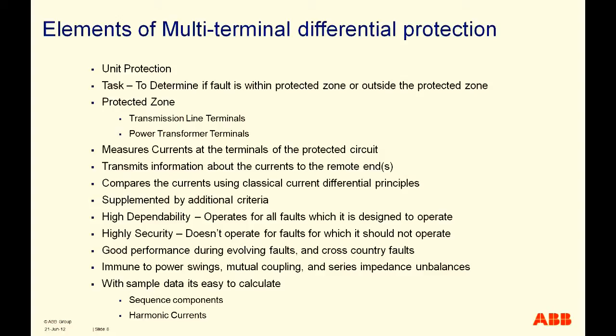So what are the elements of line differential protection, multi-terminal line differential protection? It is essentially a unit protection. When we talk about unit protection, all the differential protections are normally unit protections, and they are inherently very selective, and the boundaries of the protections are defined by the location of the CTs.